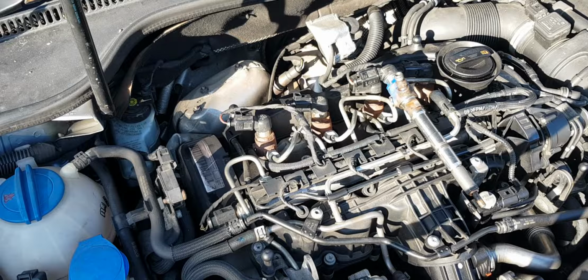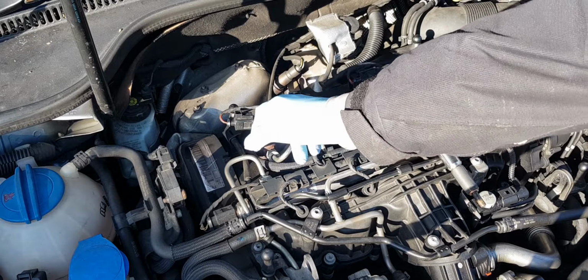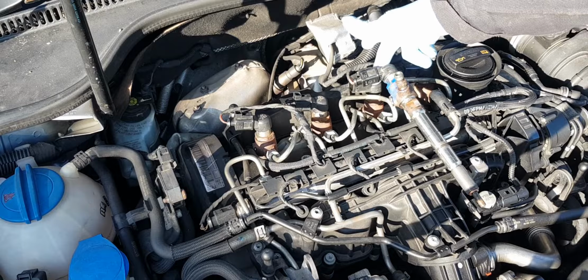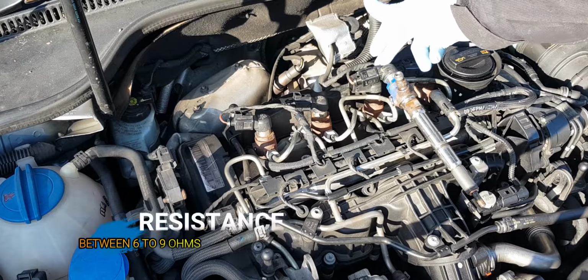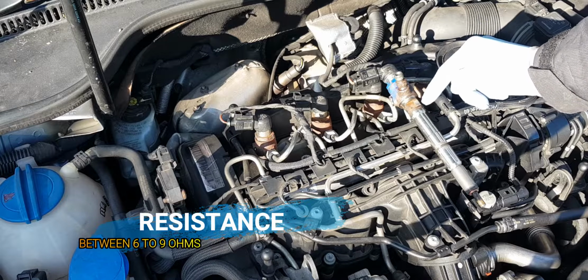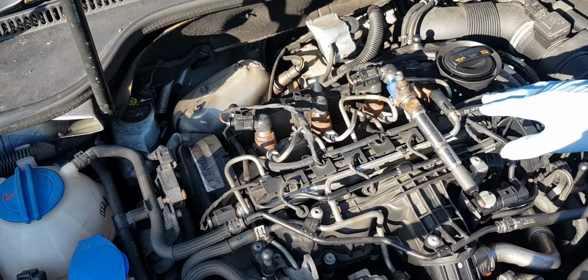We're back at the engine bay. It's about time to do a bit of mechanical work, so we have finished with the diagnostics. As I said, I've checked the resistance on all injectors. I've realized that the number 3, the bad injector, has a resistance of 6 to 9 ohms. The rest of them, including the new second-hand injector, have 200 kilo ohms. So this is the spec for these injectors.